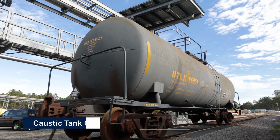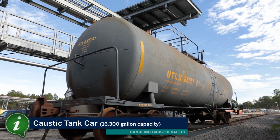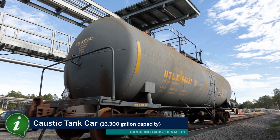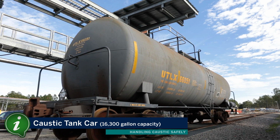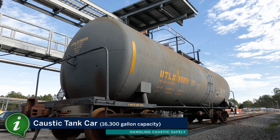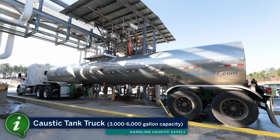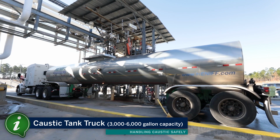Caustic tank cars are commonly 16,300-gallon capacity, constructed of carbon steel with an epoxy liner. They have an external steam coil, insulation, and a jacket, so that the caustic can be thawed before offloading. Caustic tank trucks typically have a capacity between 3,000 and 6,000 gallons.